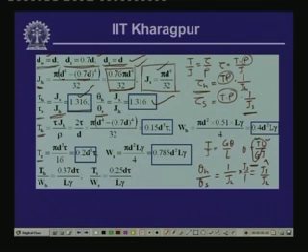Now, the twisting moment that can be resisted by the hollow section is equal to tau J by rho. This is from this particular expression, T by J equals tau by rho, so T is tau J by rho. So, rho is again equal to d by 2, and J H, as we have seen, is pi by 32 times d to the power 4 minus the inner diameter, which is 0.7 d, to the power 4, and this gives us a value of 0.15 d^3 times tau.